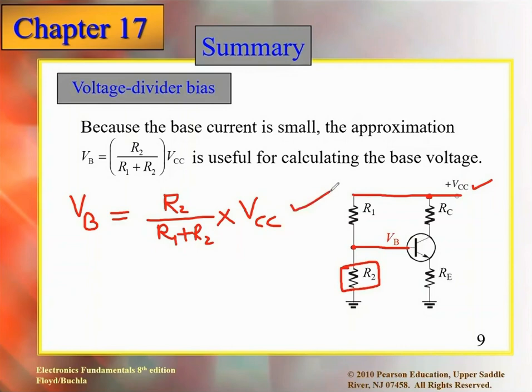So this is so easy. Whenever this type of question is given, R1, R2, VCC, RC and RE will be given to us, and I can quickly calculate VB. Once I calculate VB, do you remember the formula for VE, girls? I can say VB minus VBE. I just flipped it, because it was VB equals VE plus VBE. Do you remember? Yes. So if we subtract 0.7 from VB, we get VE, right?